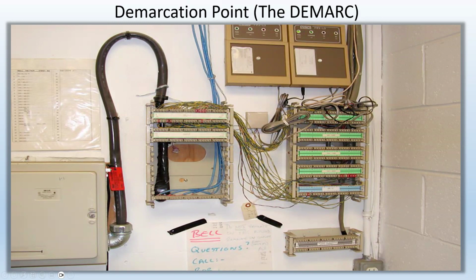Out of here, well, into here, there's a 100 pair cable, but we don't see it. But into here, from out of this demarcation device, there's a 100 pair cable. What's a 100 pair cable? Well, it's 4 25 pair cables in one jacket. Remember, the colors are the pairs or the bundles. Bundles 1, 2, 3, and 4 are distinguished by a ribbon that is wrapped around every bundle. And when you strip the jacket, you should keep those ribbons and tie those ribbons around each bundle.